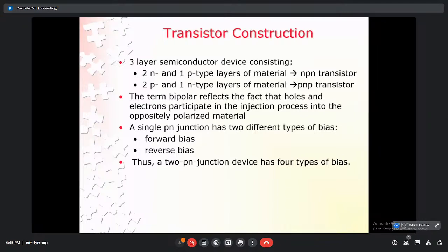And then how can the depletion region be formed, because we are doing the biasing like that. Simply you can see, for normal operation, the emitter to base junction is forward biased, whereas the base to collector junction is reverse biased. Because of forward bias, the charges will move on or try to pass on. But whereas the base to collector is reverse biased, it will stop or resist. Because of that, a depletion region is formed where recombination of electrons and holes takes place. This is a beautiful concept we will discuss in coming slides also.